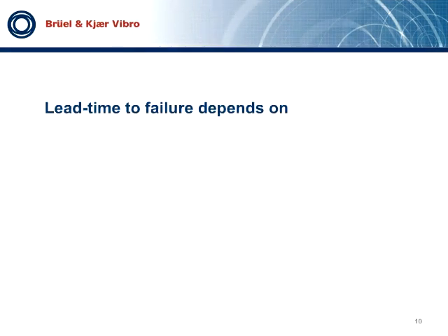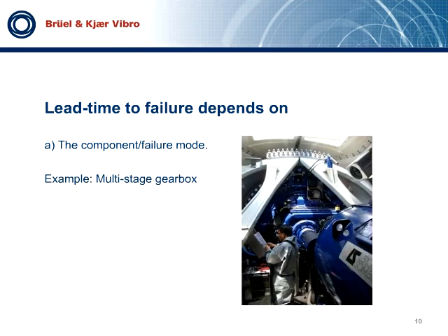So, what does lead time to failure really depend on? So we can say, okay, A, it depends on the component or the failure mode. An example could be a multi-stage gearbox. The detection rate for different failure modes is quite different from stage to stage, and thus the lead time to failure is quite different.